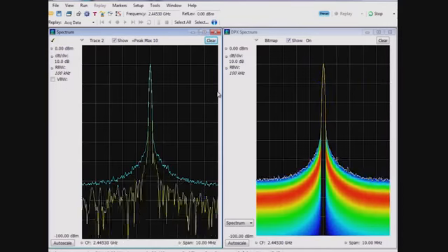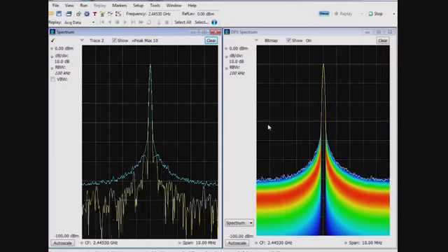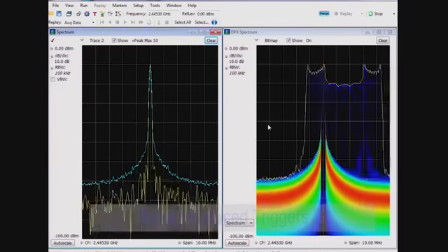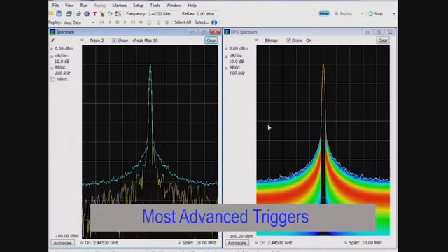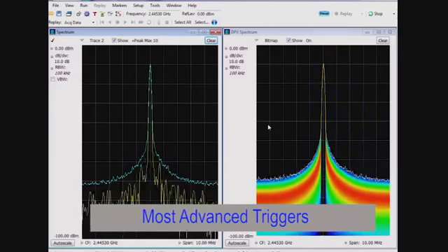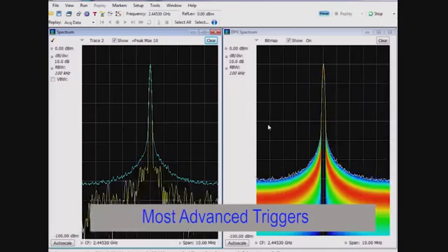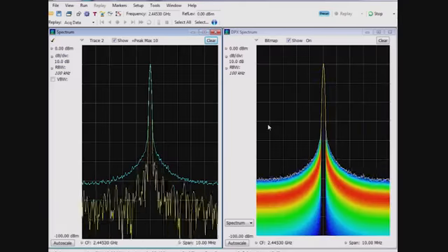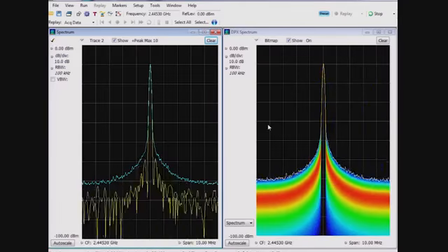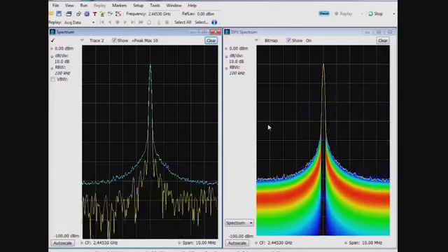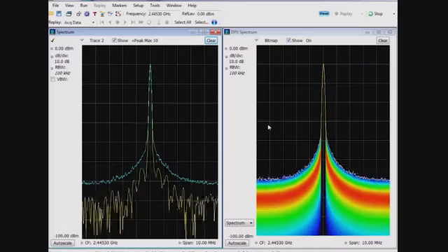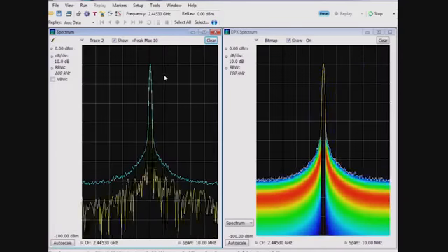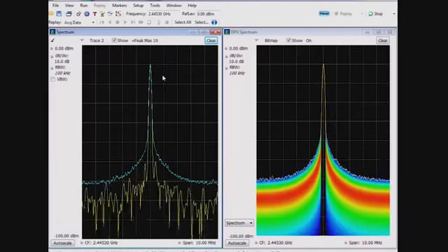One of the other key features for any real-time spectrum analyzer is to have frequency selective triggers. Here, Tektronix leads the way with an easy-to-use DPX density trigger, as well as having frequency mask trigger, frequency edge trigger, and applying time qualification to any of the instrument's triggers. For this demonstration, the DPX density trigger, also called "trigger on this" in the user interface, lets you trigger on any signal that you can see on the DPX screen within the RSA's 110 MHz bandwidth.